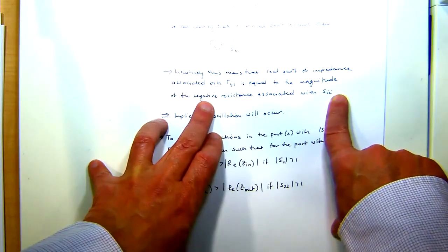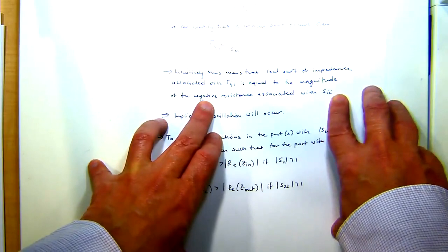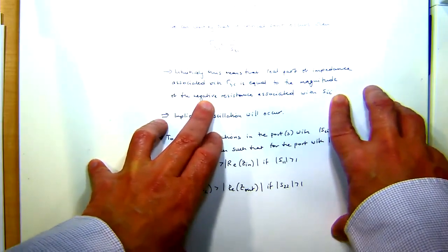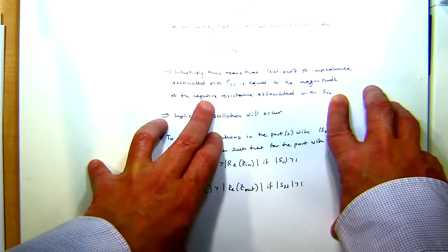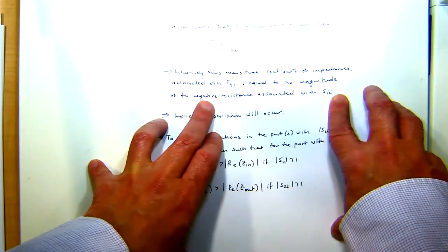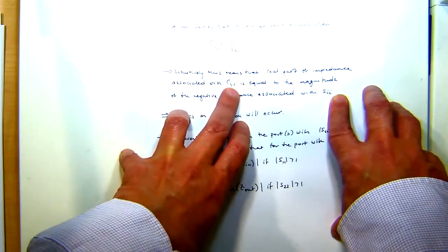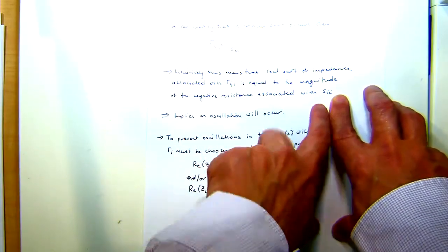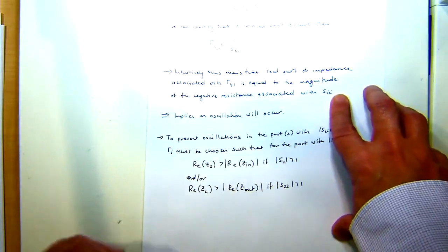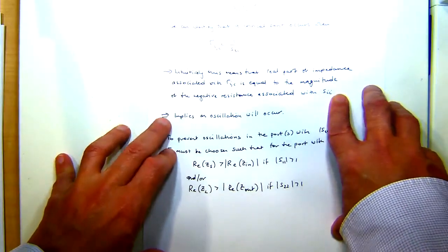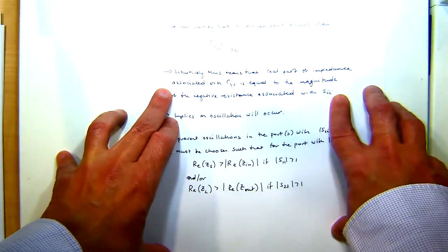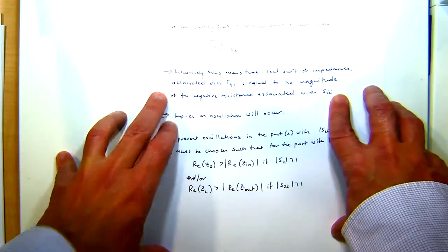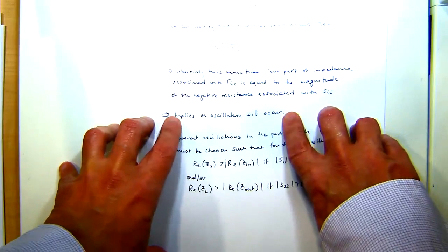So the scattering parameter, you can think of it as having a negative real part because it's actually an amplifier, right? And what we're saying here is that the gamma is exactly equal to that, and it's cancelling it, and that's why it's tending to infinity. And in most cases, remember what we said, that in real systems, nothing ever goes to infinity. Generally what happens is you get an oscillation.